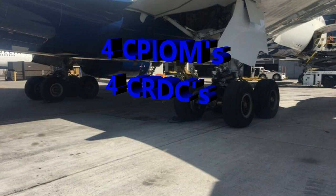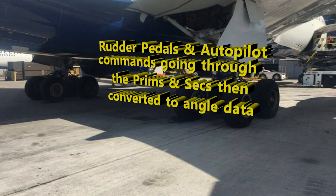Keep in mind, with the pedals and the autopilot, those commands are actually going through the primary and secondary computers, your prims and secs. It's going to take that combination and convert it into an angle, because that's the objective. By the way, there are 2 actuators on the nose wheel steering system, so you can operate and move to that commanded angle.